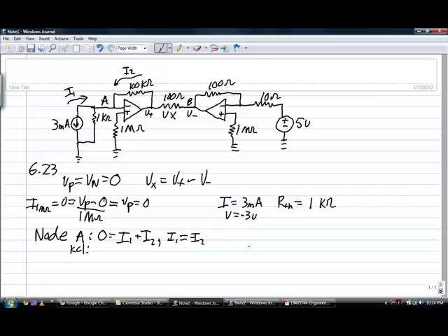So redrawing the circuit right over there, we'd have our ground going up into a voltage source. Now normally these signs should be the other way, however we reversed the output, so it's okay to draw it as this. And then we have our resistor, 1 kilo ohm, right here. And that'd be the terminal at A. So using that, we can help us calculate this V sub plus right here. So back to our node equation right here, let's finish that up.